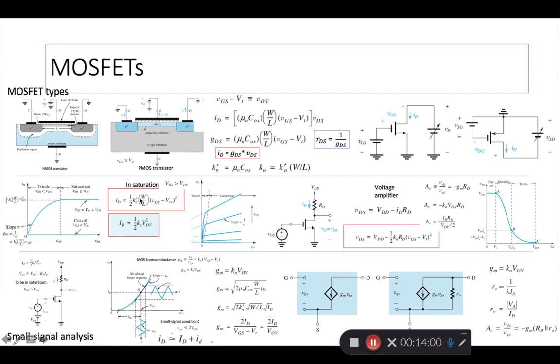So this relationship is important, and this only holds when we are in saturation, which means the drain to source voltage has to be greater than the overdrive voltage. That is the basic condition that defines saturation.